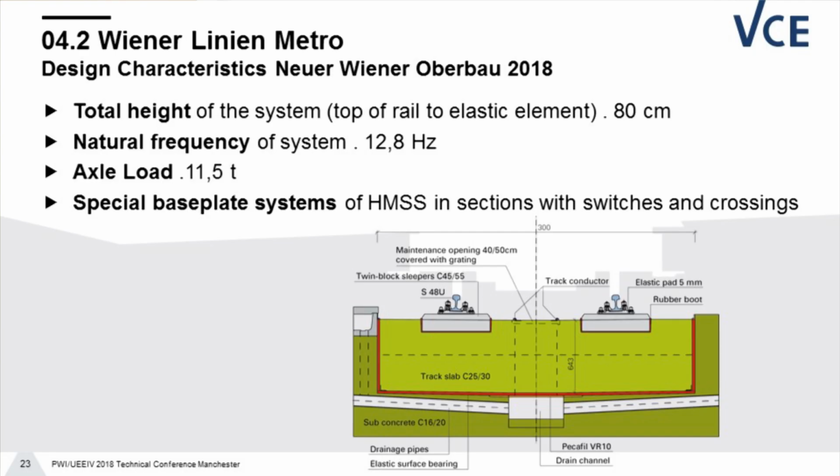As I already said, we have increased height. You can see that the mass block is much higher. We still have the B-block sleepers. The frequency now comes down to 12.8 Hertz. The axle load increased. And in switches and crossings, we have a special baseplate system that was implemented.